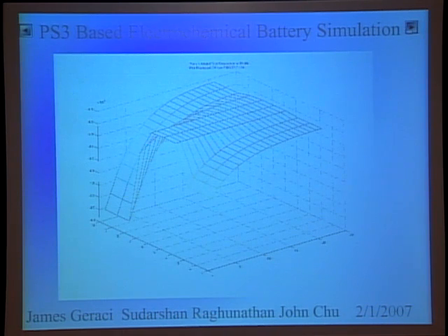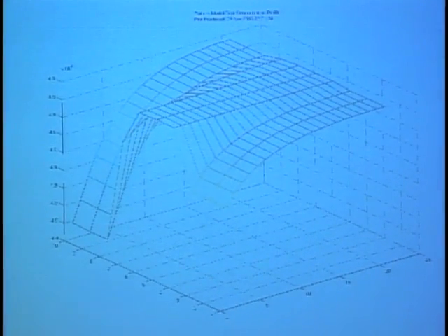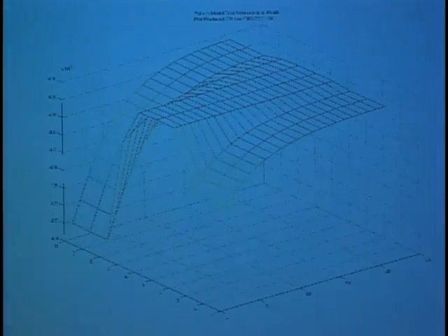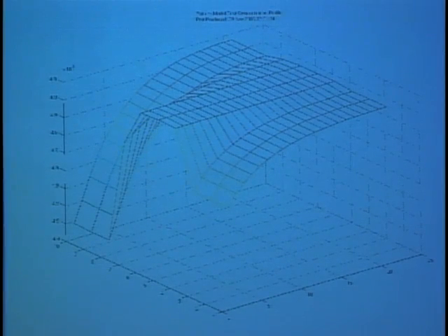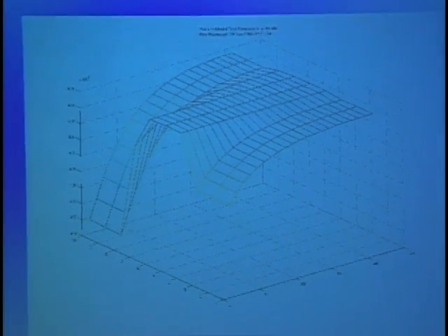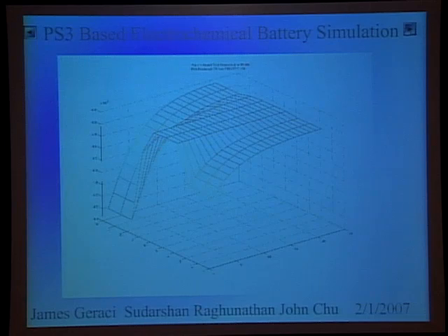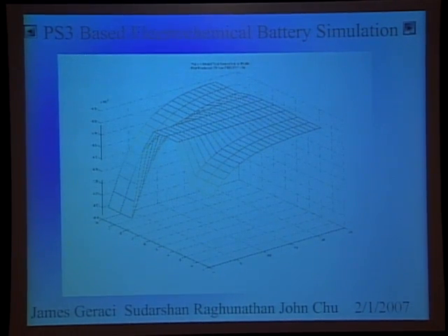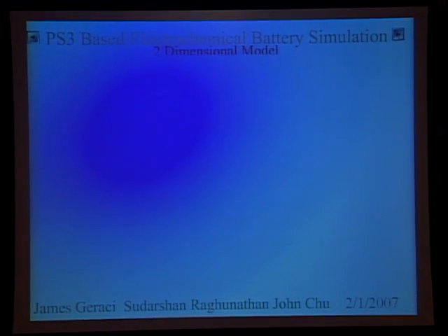This is the kind of output that you could get from this type of battery simulation. What you're looking at here is, the left-hand side is the electrodes, the top of the battery, and the height of the battery goes along that way. You see that as you discharge, the acid concentration at the top of the electrodes is consumed, where you're drawing current out most readily. So physically, the simulation kind of makes sense, even if my speech didn't.